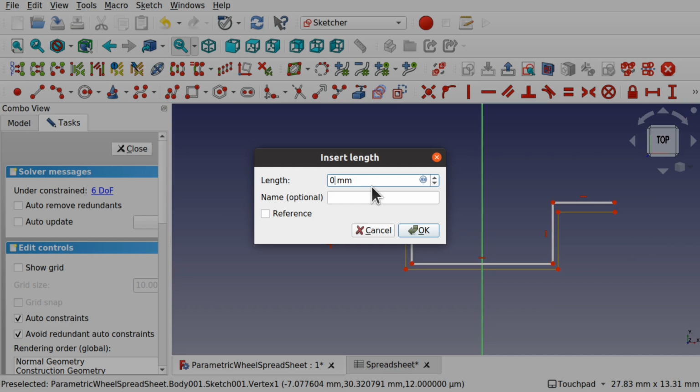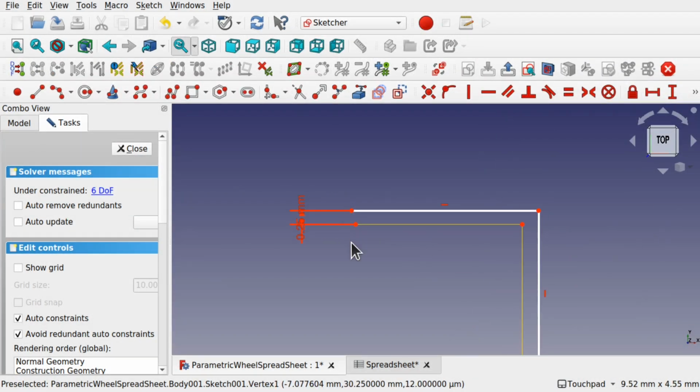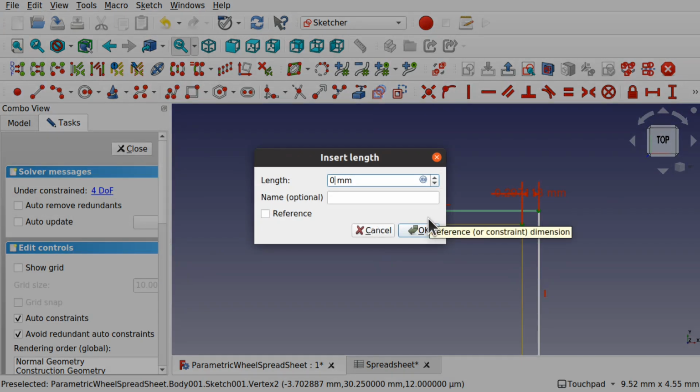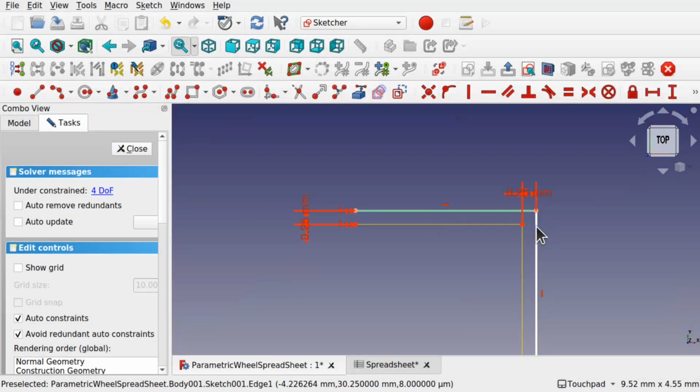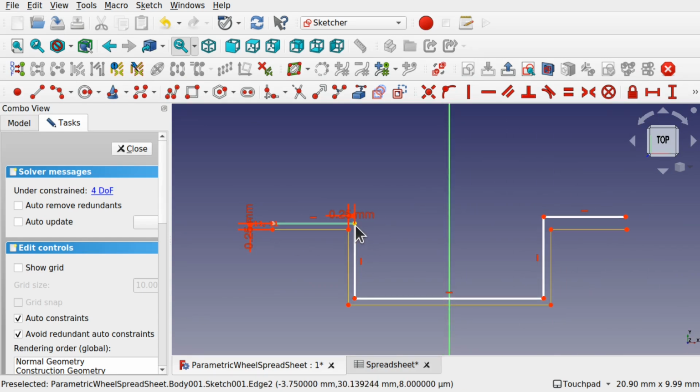and placing our tolerances, so 0.25 millimeters, like so, making sure that these two are in line, and these two, let's set a length of 0.25, and making sure that this point and this point are in line, and this one are in line.